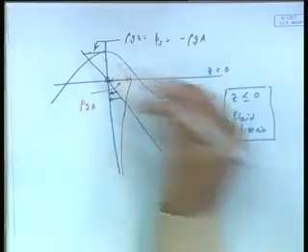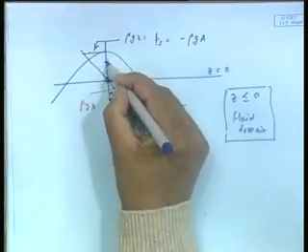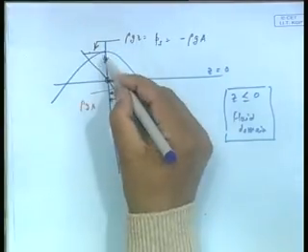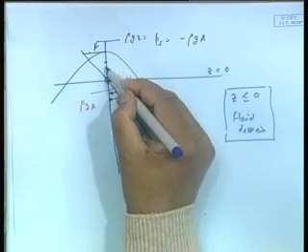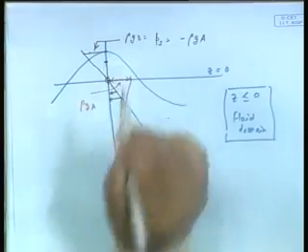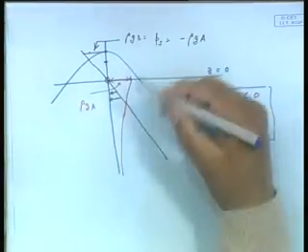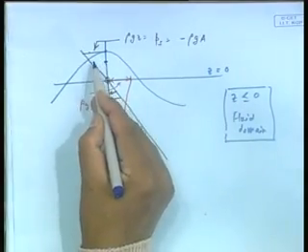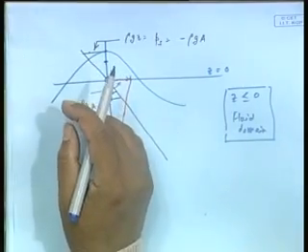What happened here? I want to know physically what is the pressure at this point, for example. How do I find out? Let us say this is 5 meter, I want to find out what is my pressure 1 meter below the crest. Now, if I were to apply only rho g z by this formula, what do I get? A completely absurd result of a negative pressure.